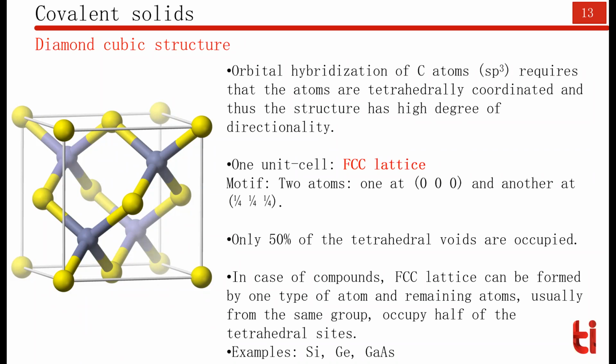If you focus only on the yellow balls, the yellow balls represent the FCC structure. Apart from the yellow balls, you also have 4 gray balls. If you closely look at the positions of these 4 gray balls, you can clearly see their positions are actually the tetrahedral sites.